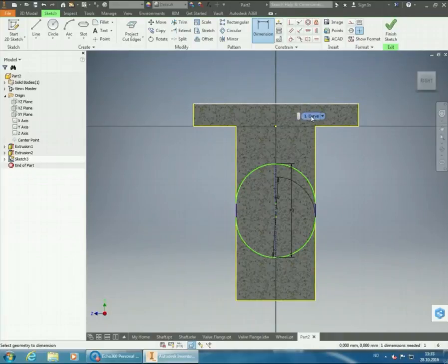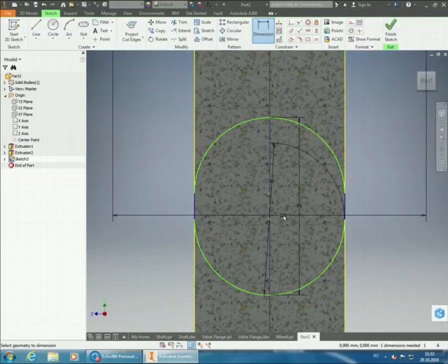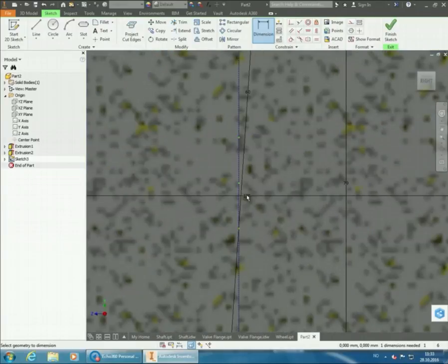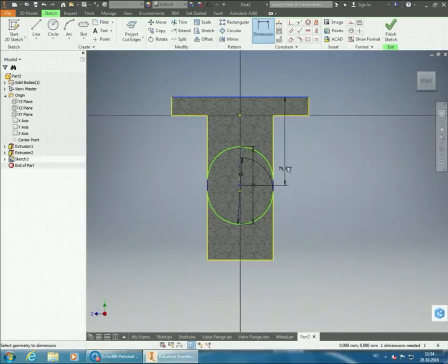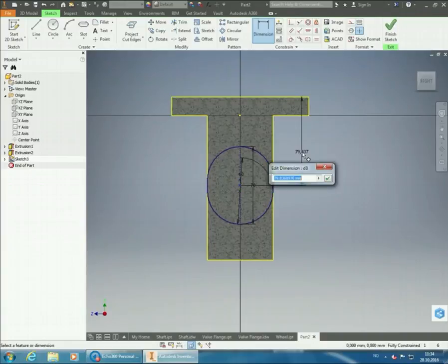So we'll click on that one, and then it will be wise to zoom in here in order to hit the correct one, because in the middle here we have 3 green dots, and it's the middle one of those dots we want to hit. So zooming in a little bit might be wise, and we're going to hit the middle of the 3 green dots. You can zoom out again and set it in here, and the length is going to be 82 millimeters.